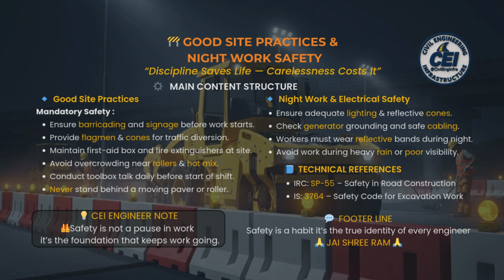Check generator grounding and safe cabling. Workers must wear reflective bands. Avoid work during heavy rain or poor visibility. CEI engineer note: Safety is not a pause in work, it's the foundation that keeps work going. References: IRC SP 55, IS 3764.